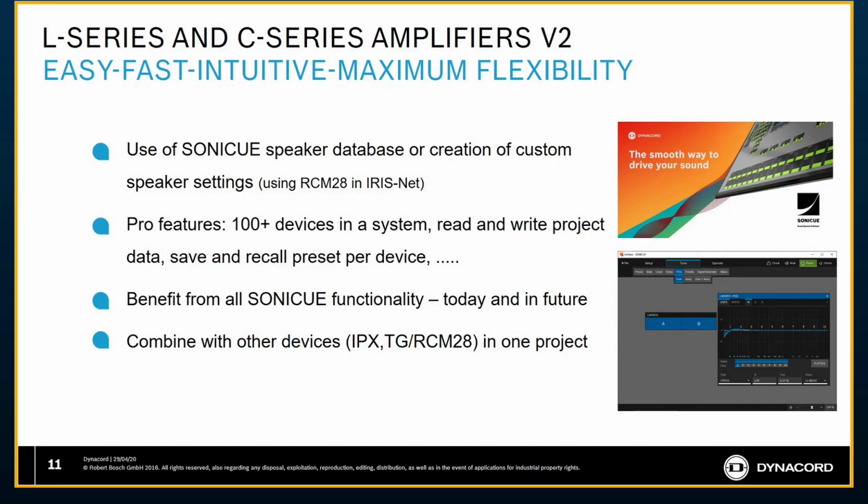Previously with LNC series amplifiers, we were all accustomed to using MARC software, which stands for multi-amplifier remote control. We were only limited to 16 amplifier channels, so most likely only 8 amplifiers. So now we're able to get 100 plus devices. Plus with MARC, you were only able to write to the amplifiers. You weren't able to read, which was kind of a bit of an inconvenience.